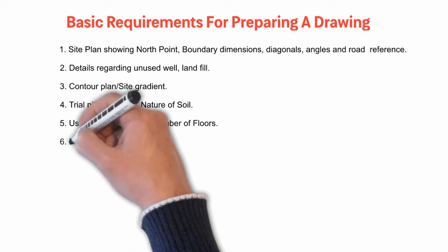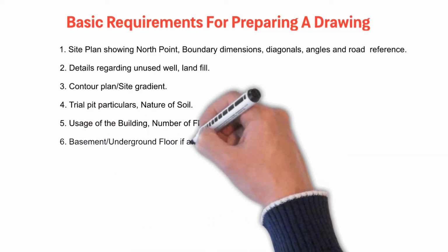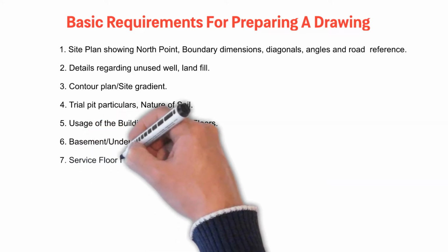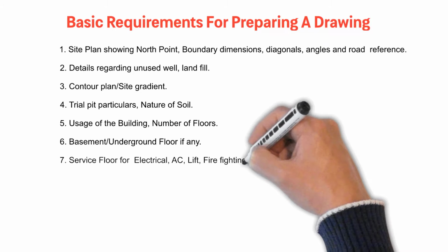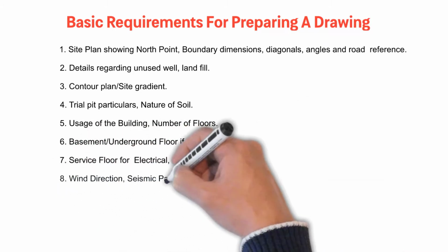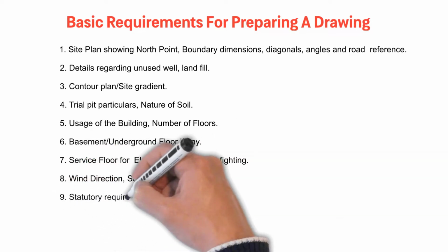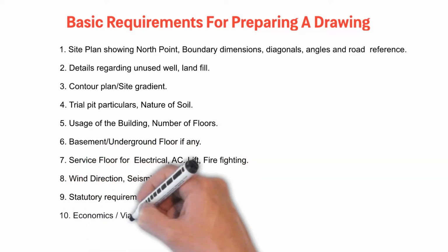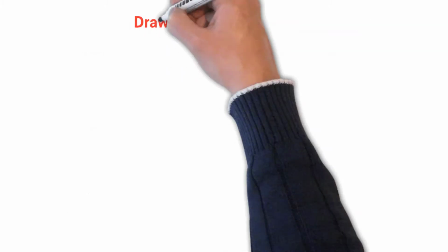Also, we should finalize the basement, underground floors, whichever it is, if any. Then we have to plan for the service floor for electrical, AC, lift and firefighting. We should also collect details regarding the wind direction and the seismic particulars of the area. And we should also follow the statutory requirements, and we should have a study about the economics and the viability of the building.